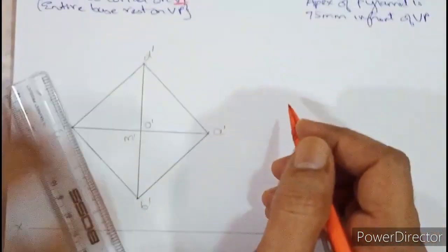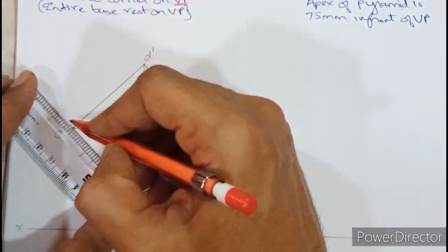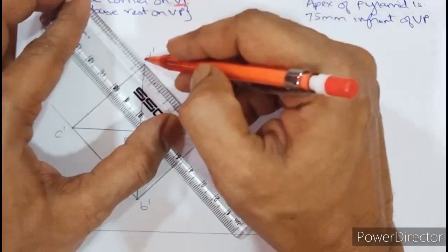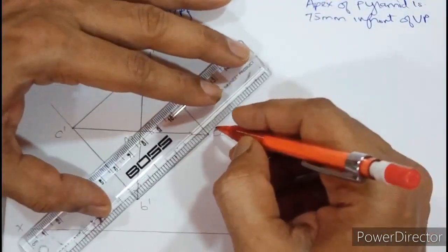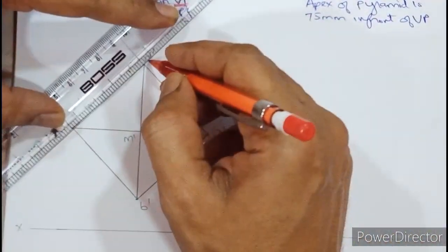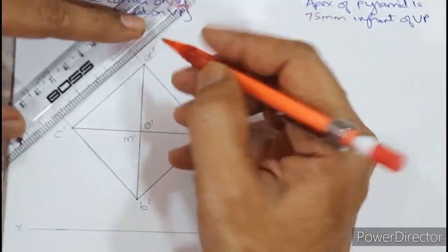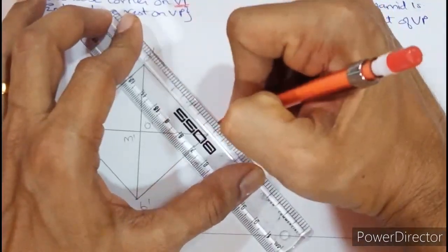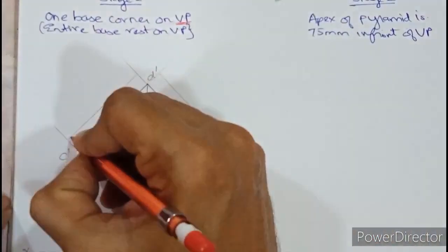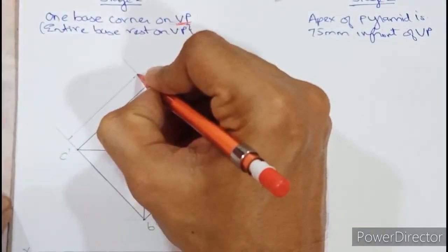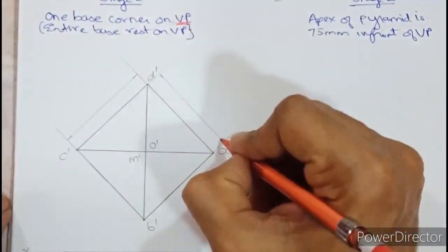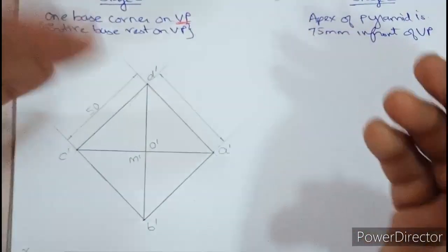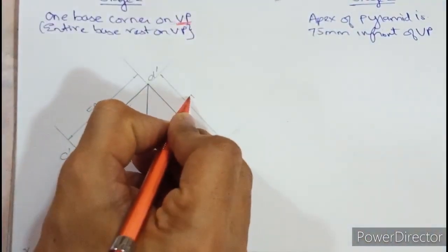We need to show dimensions at two adjacent sides of a square. So whenever you draw a square, you need to show dimensions of the sides at two places. So here, draw medium dark extension lines and then show dimension line at both the places, with standard arrow marks, thin and long, and write 50 above the line. So the 50 is over here. This is called above the line, and here above is on this side. So you need to write 50 like this.